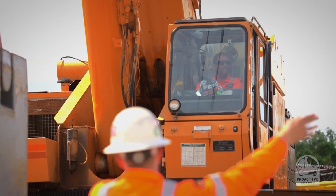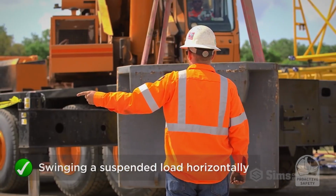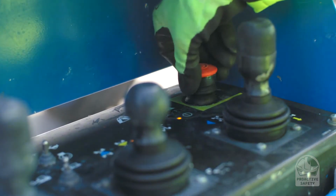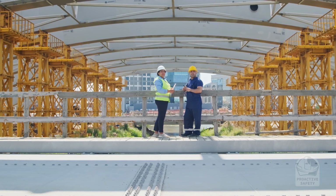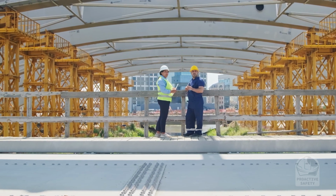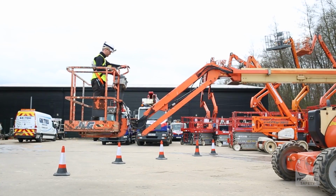Hand signals and emergency stop. Common hand signals for stop, move up, move down, and other indicators are highly important. Make sure that the emergency stop button works in order to stop the equipment in critical situations. Effective communication between operators and workers on the platform is always important.